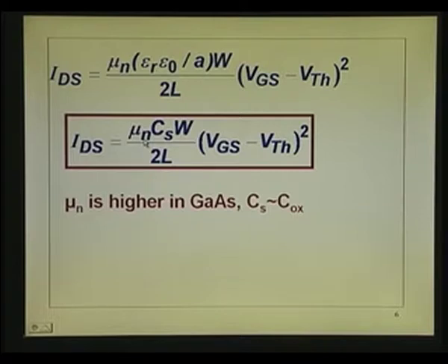But unfortunately, the barrier heights are small in the case of silicon, because the band gap is 1.1. If you take two-thirds of that, about 0.7, 0.75. That is why, and also your A star etcetera are large. So, J0 is large in those cases. So, you do not really talk of a MESFET in the case of silicon, but you can talk of a JFET in the case of silicon. The same equation holds good in the case of a JFET, absolutely no problem.